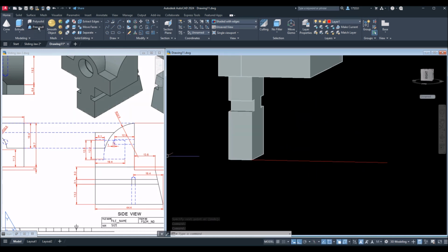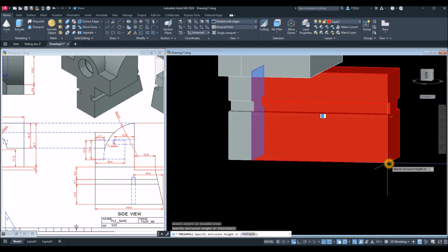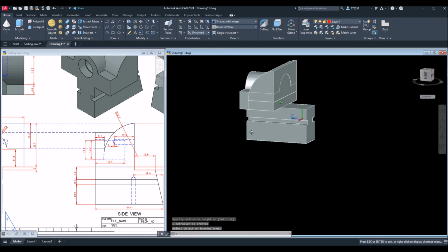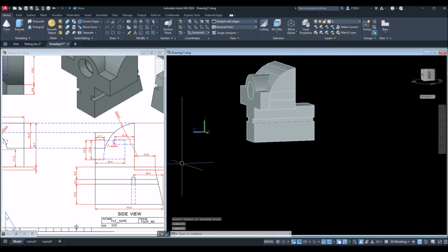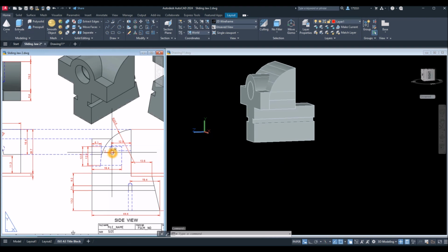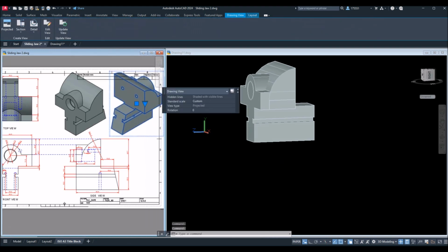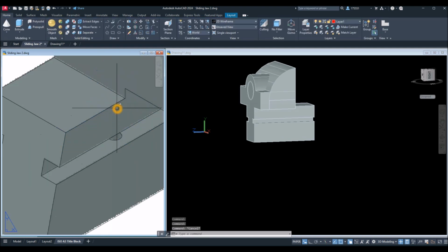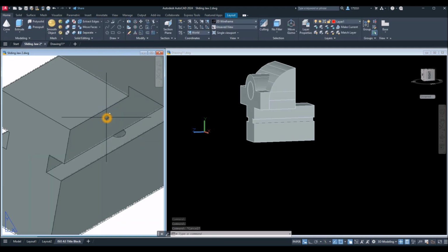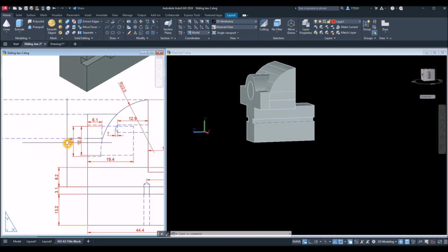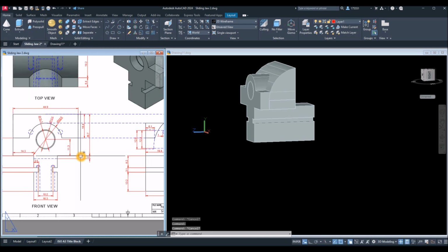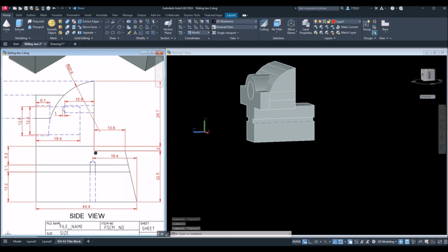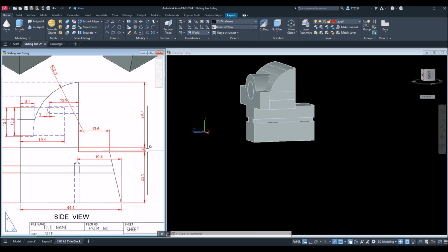Press pull command again. So press pull command, hover over this face and extrude it up to this direction. I'm just gonna change back my layer to 0 layer. And as you can see here, there's a gap. There's a cut here. See this one? For 2 units, looking from here. So 2 units here. And also looking from side view, you can see that there's a cut here. So this one.